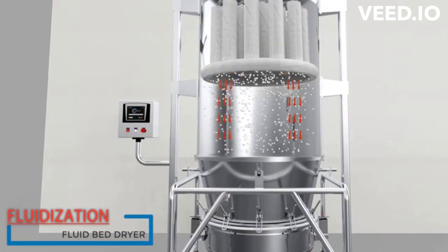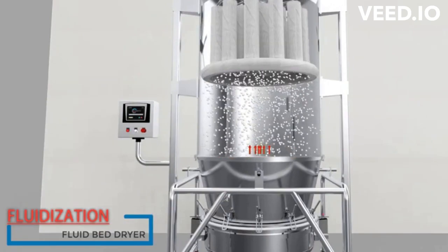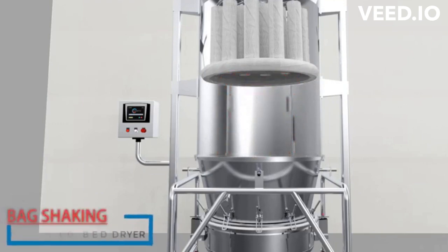Solid particles are fluidized with hot air. Heated air transfers the heat duty to the material to help with the drying. The suspended solids' residence time for drying is in the perforated chamber, which leads to the finger bag, which separates the air from the solid